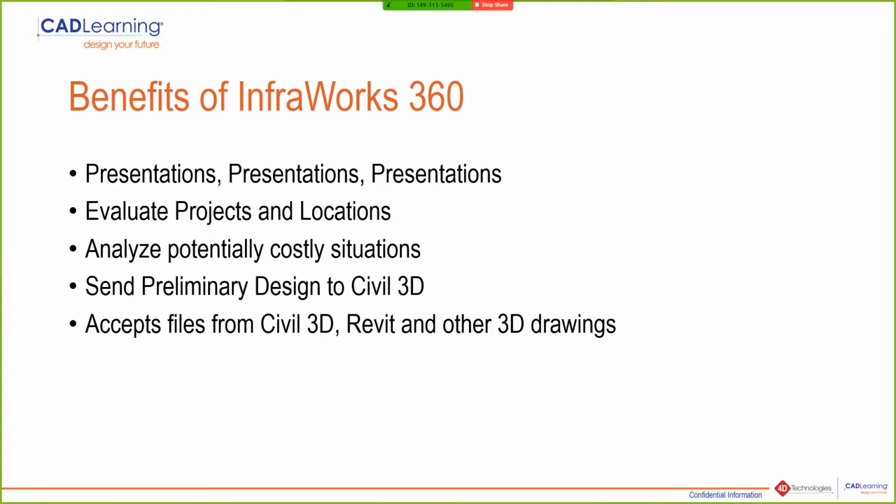So it accepts files from Civil 3D, obviously, and it accepts Revit files. So let's say your client has a commercial building or a residential subdivision going on, and they've contracted with a structural engineer and an architect, and they use Revit. If they've got the buildings already done and modeled, you can take those Revit files and import them into InfraWorks 360 and place them in the lots where they should go. I don't always suggest doing that at the preliminary stage.